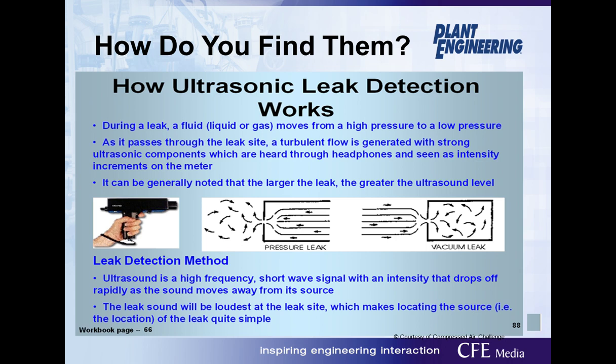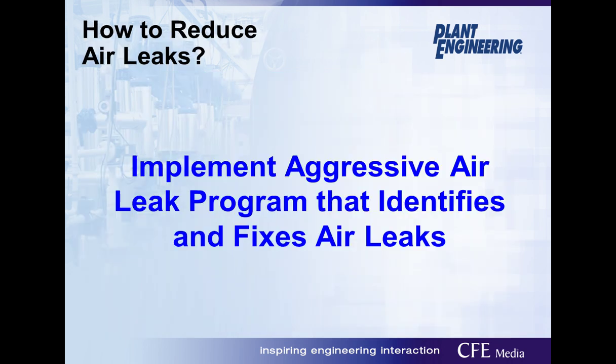So it makes finding leaks very effective, either from a pressured system, which you see on the left, or a vacuum system, which you see on the right. So anytime you're changing from a high pressure to a low pressure, you're going to get ultrasonic waves that come off of this. And the detector is a great way to go through and find those. And then, of course, how do you do it?